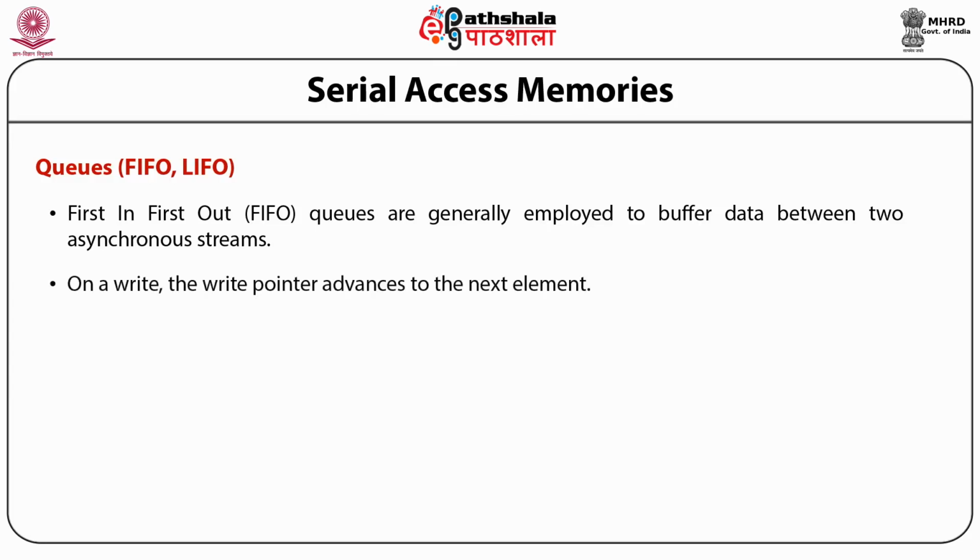On a write, the write pointer advances to the next element. If it catches the read pointer, FIFO is full. On a read operation, the read pointer advances to the next element. FIFO becomes empty again on catching the write pointer.